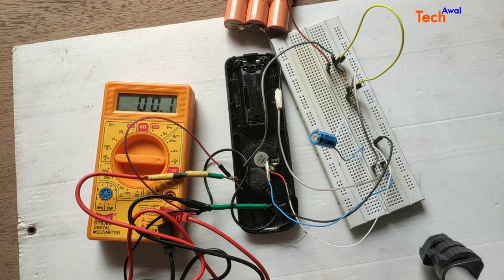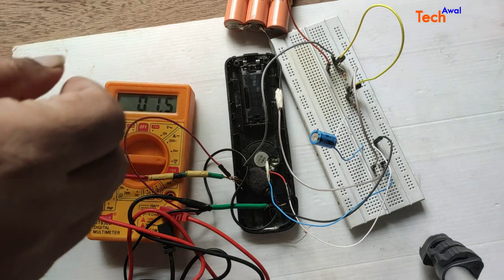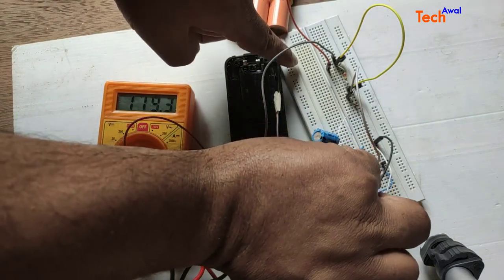So this is IE of the NPN and IC. So both we saw. 127 it goes, and around 102 milliampere the transistor goes cut off. So from 127 to 103, I think in that period the capacitor is discharging, and beyond a limit it is switched off. So next we will measure IB, then we will measure current in the capacitor.